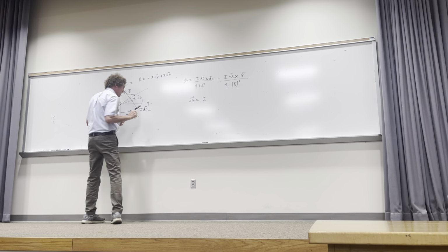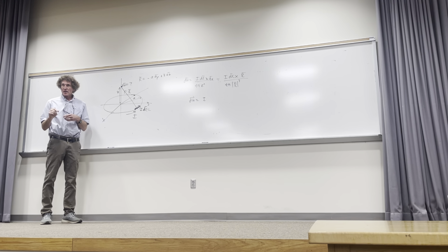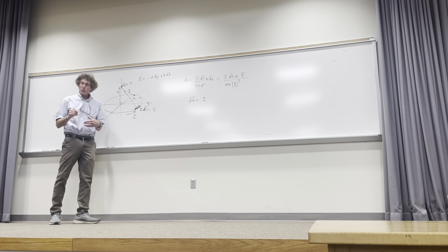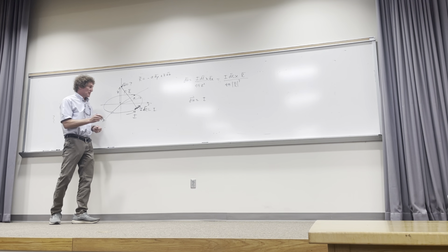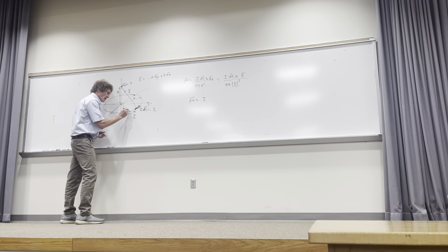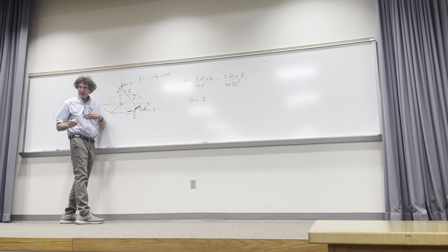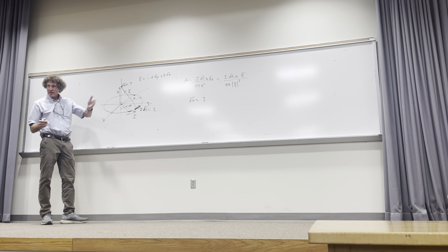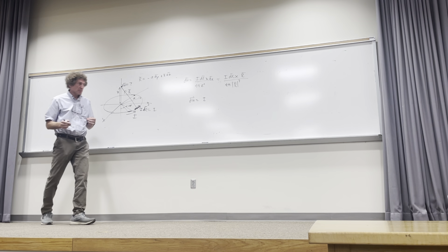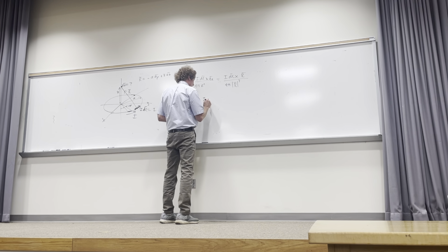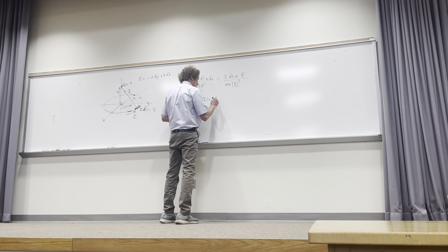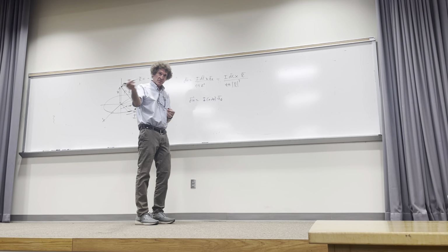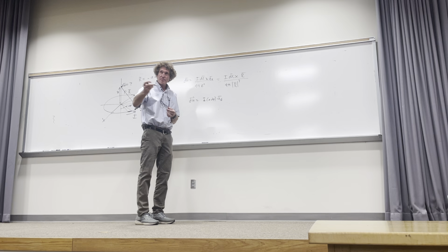I dL is what? I didn't put it down here. What would that be? Well, you've got to give me this. It's got to have an I in front, right? What is dL is what I'm getting at. Think about this. Remember the wiper arm length from the center? If it moves a certain distance, what is that? This would be d phi, right? And it would be a d phi would be the wiper arm tip length, right? So it would be a d phi, and it would be in the a phi direction, right? a phi is the direction the current is. Do y'all follow me in this class?